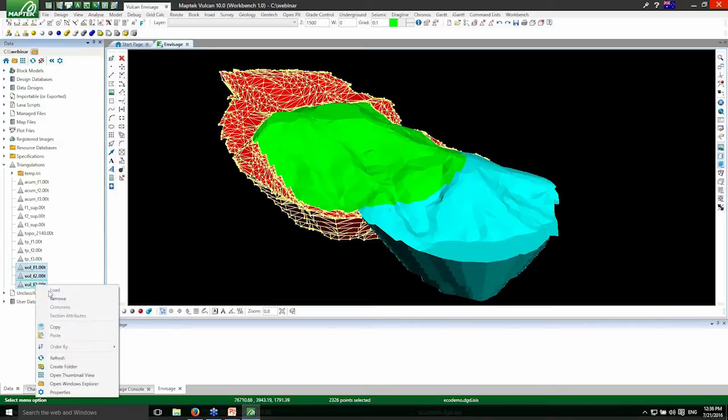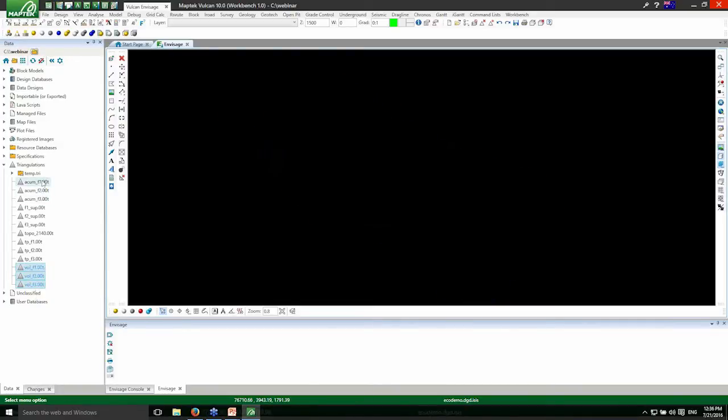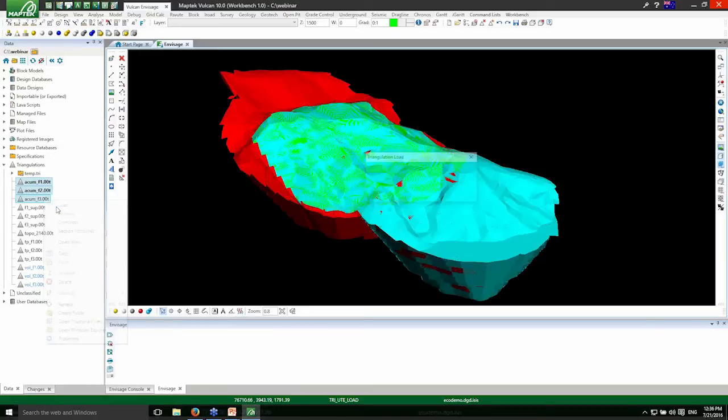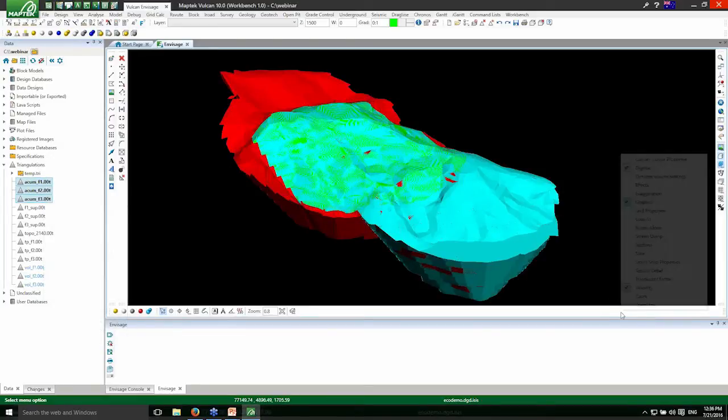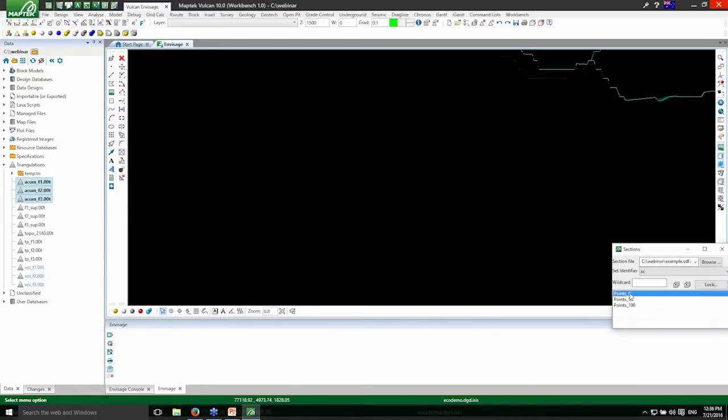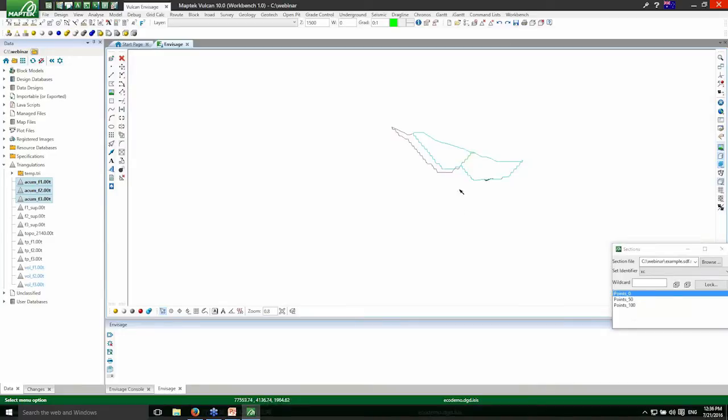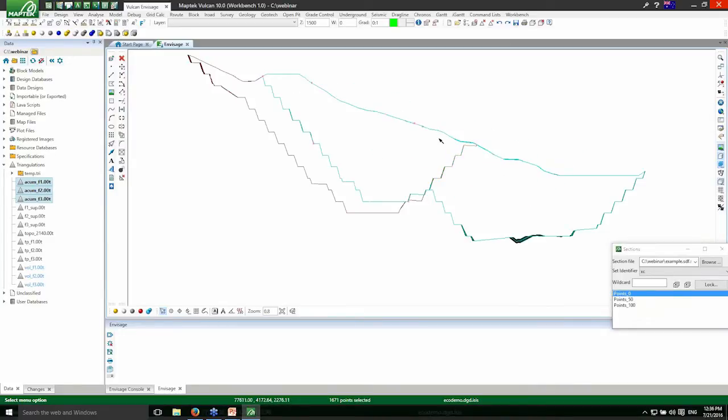But we also have some customers that use the accumulation solid. What I mean is, let's put this one maybe in a section view. Pushpad 1 contains all the blocks for pushpad 1, obviously, but pushpad 2 is accumulated, so we have blocks for pushpad 1 and 2, and pushpad 3 includes 1 and 2. So obviously we need to play a little bit with the priority here in order to get the right flag.